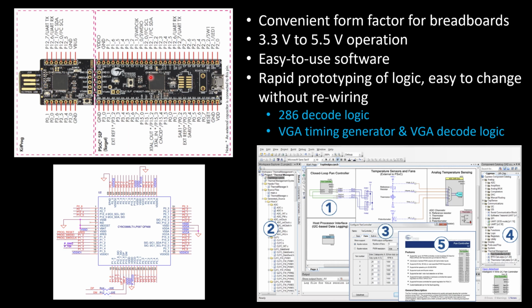And the actual chip on here, this PSoC chip, is this one here. Probably can't read this in the recording, but it's a CY8C5888LTI-LP097. Anyways, that's the actual PSoC chip, and they've just put it into this breadboard friendly package. From that package, I've got a little USB port that I can use to connect USB devices to it. I've got this USB over here to actually program it. If I snap it apart, I can put little pin headers and just connect here with a simple cable when I need to do programming.